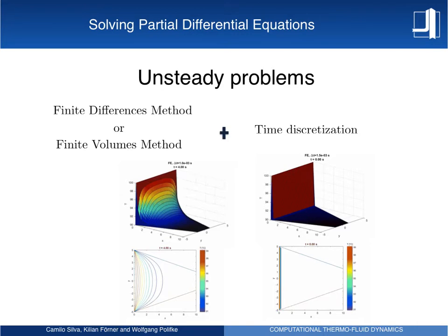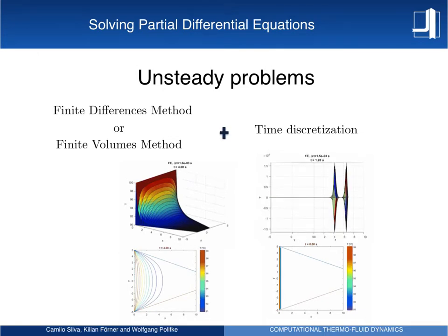But what happens if you actually do not choose the time step as you wanted or as you should have? Then the solution is going fine, you are happy, but suddenly everything blows up, and then game over. If you see in here, it's the same thing, everything looks fine, but suddenly in this region you will have problems and everything crashes. And it's a very good idea to know from the beginning at least good estimates on which is the delta T you want to use to avoid this kind of explosions.